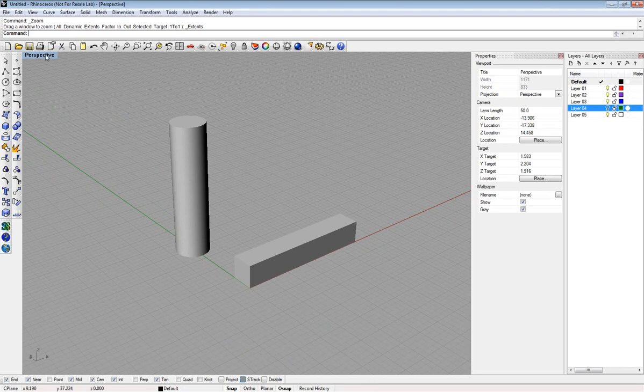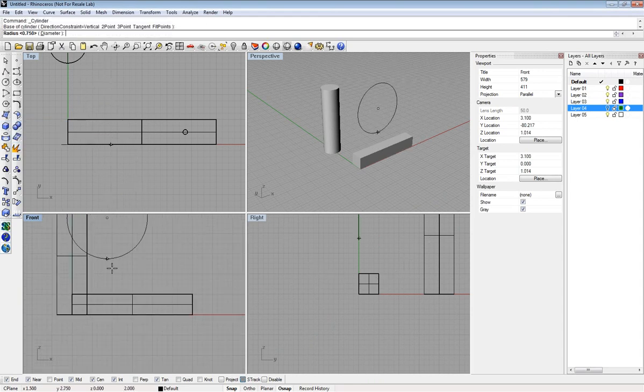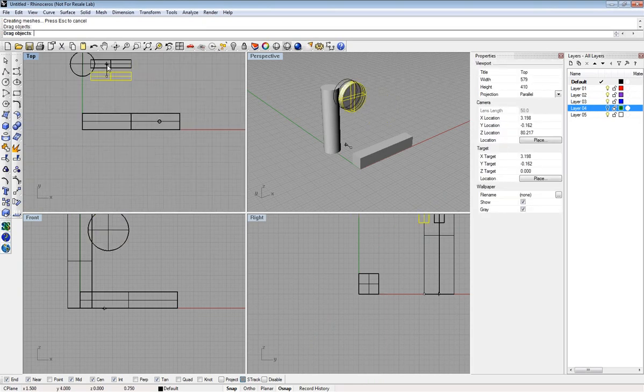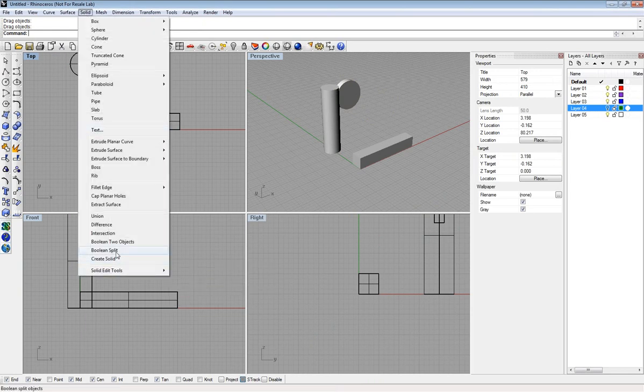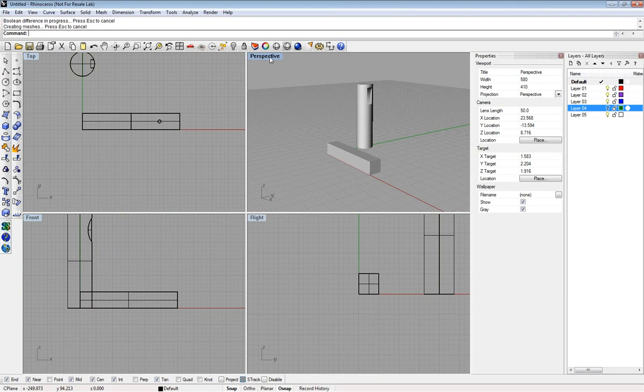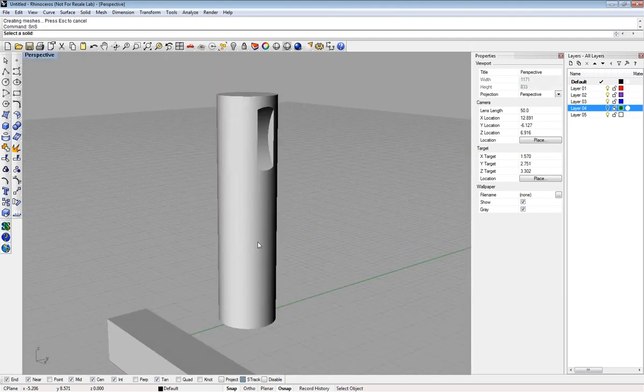So what I'm going to do here is insert a keyway into this shaft by, oops, so I'll go back to the solid menu, solid, oops, difference. I'm going to subtract this key or this cutter shape from my model, which gives me a keyway in the side of the shaft.